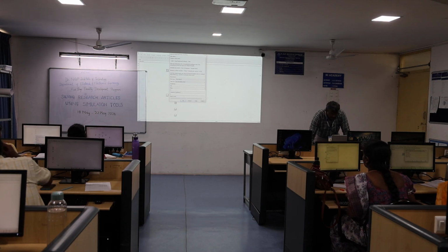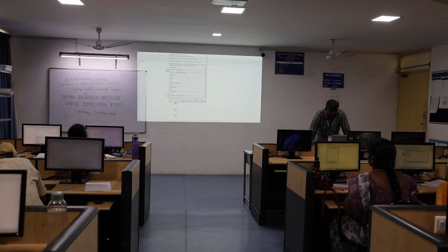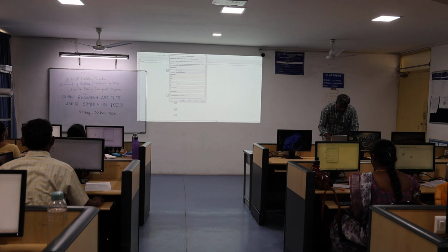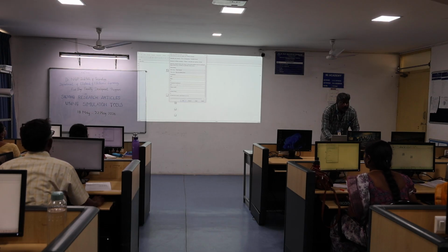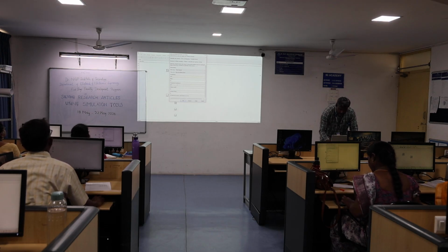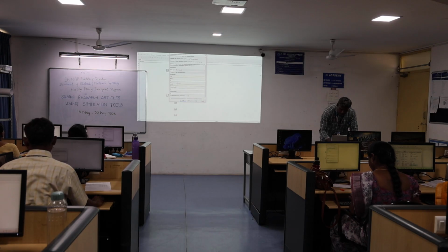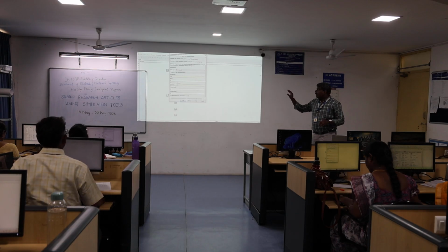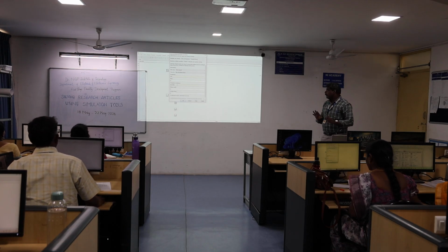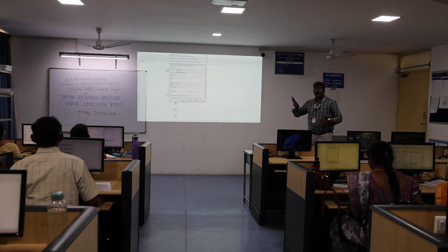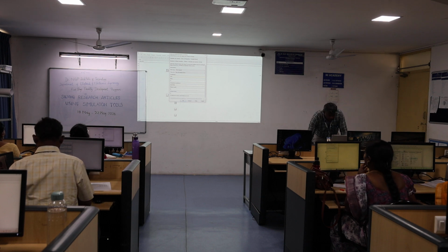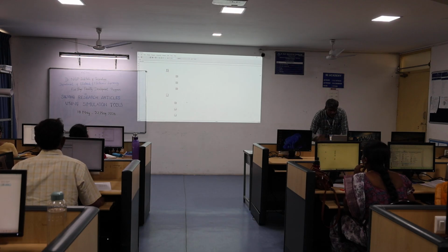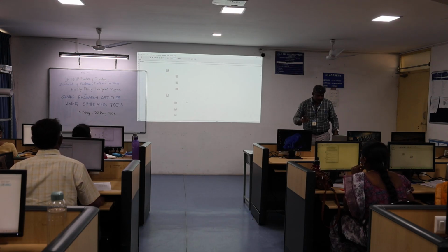Again, here you have to give the supply frequency, right? 2 pi f, that is radian per second, 2 multiplication star, pi value small letter p and i, into 50. So 2 pi f, here you have to enter the fundamental frequency value, right? Operating frequency we are going to enter into the carrier signal. So carrier frequency is always fixed, right? You don't change the magnitude of the carrier frequency.